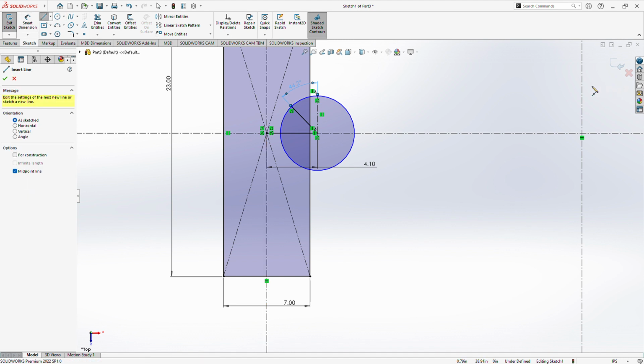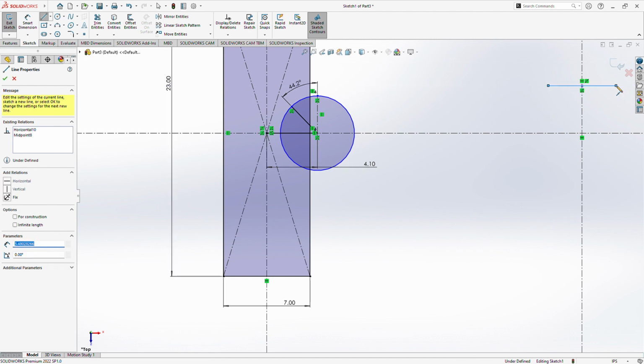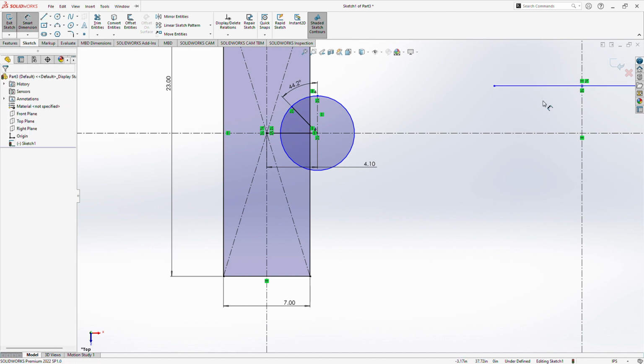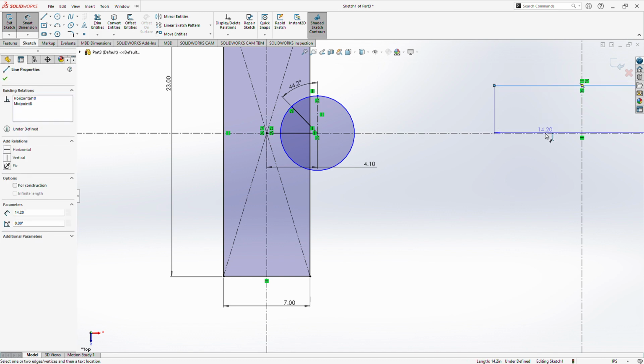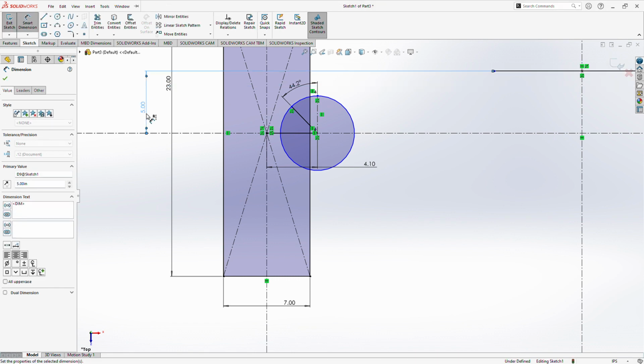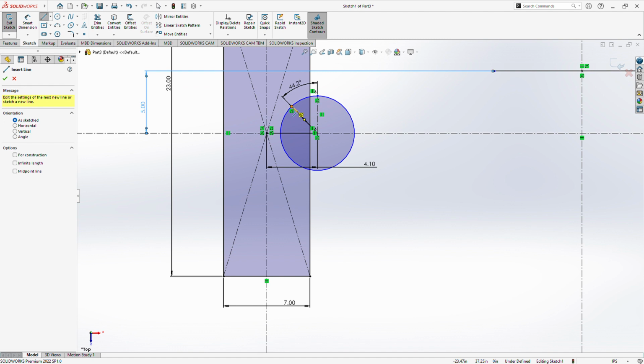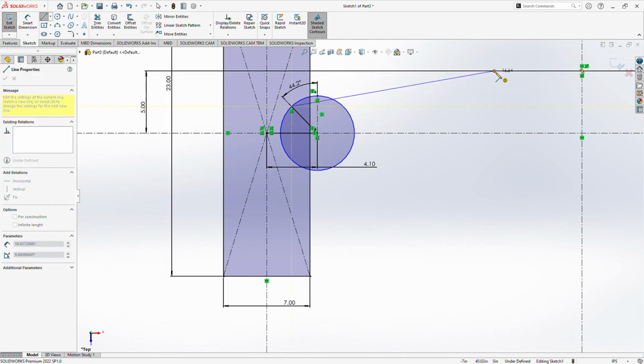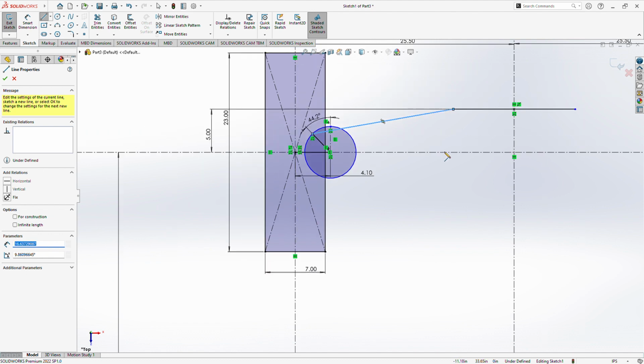We'll make the rack, which will be situated at the center of the vehicle. Its length is 14.2 inches and it is 5 inches in front from the center of the tires, line joining from the center of the tires. Okay. Select line, connect the steering arm to the rack. This line here represents our tie rod. Copy this value. We'll be needing this value in future.